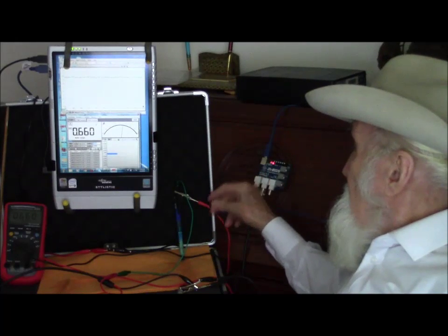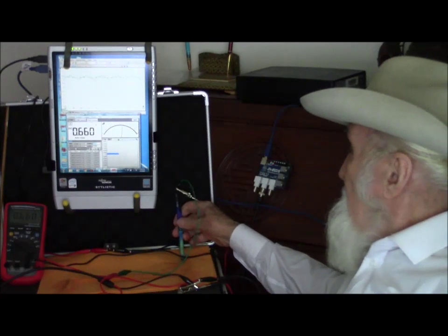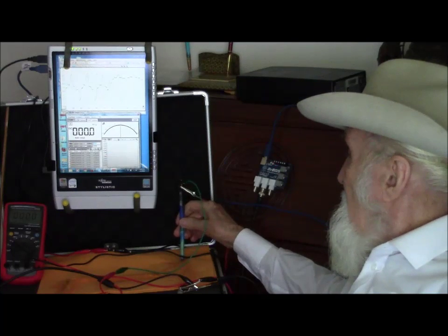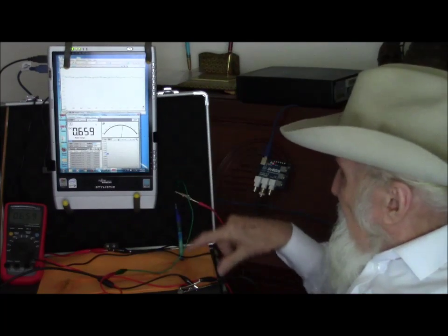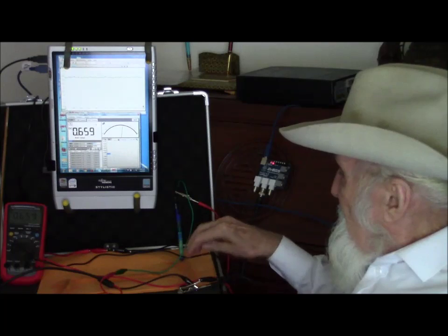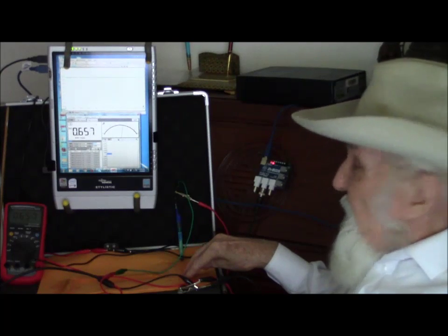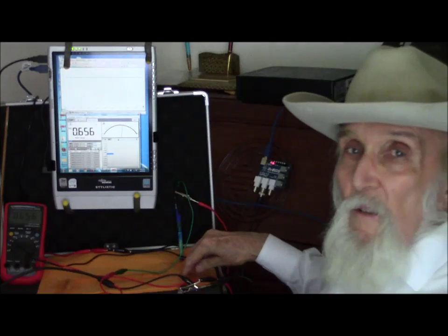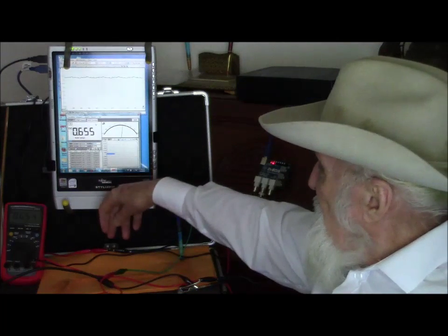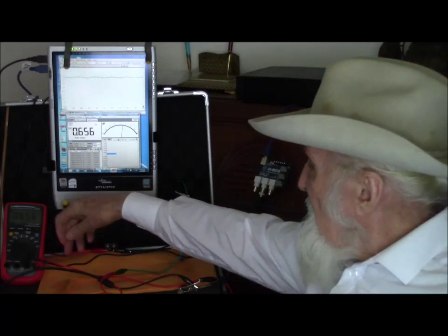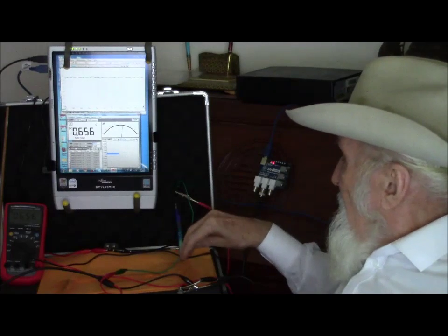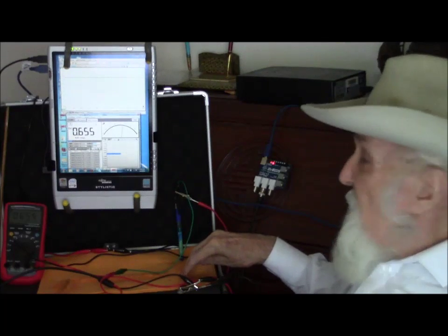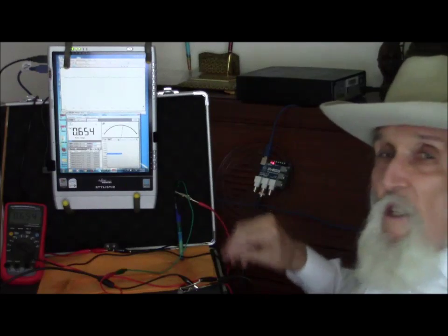The voltage is the measurement between the potential of this, through the measuring circuit, to the potential of this, which is the nail which is protected from corrosion by the charges that are being impressed into this nail, travelling through the electrolyte and being received by this nail to complete the cathodic protection circuit itself.